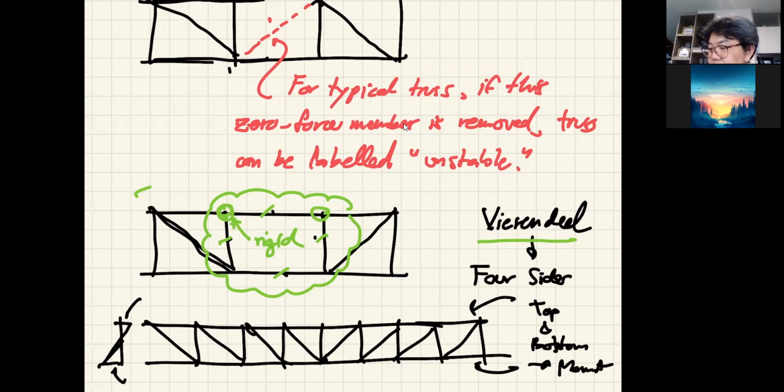And you will find out, most of the time, that the diagonal member that carries the largest force will be the one closest to the support, because it takes the shear, and the maximum shear of a simple beam is at the support. You can say the webs take the shear because the shear stress looks like that. It's maximum in the middle. So if you are going to have a case like this where you don't have the member in the middle, you better ask them to remove something closer there. It would be better.